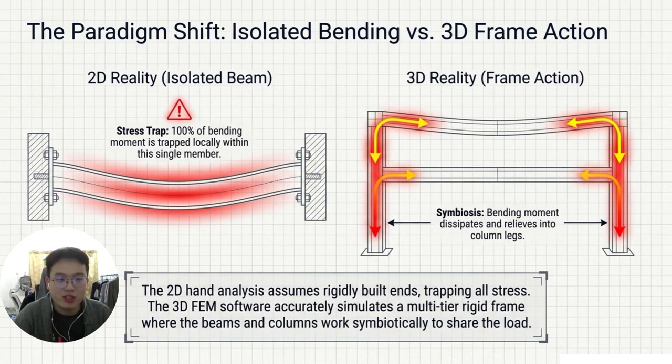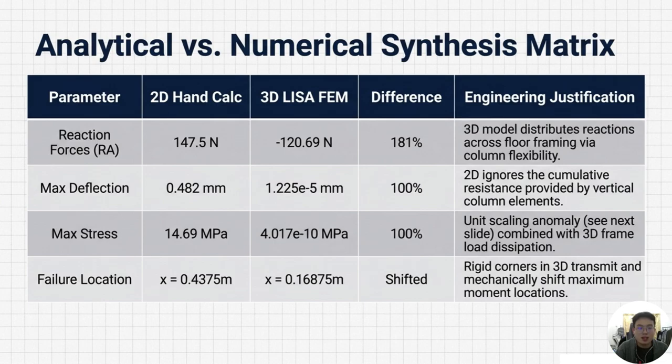This slide shows the deformation behavior of the structure under loading. The largest displacement occurs near the central region of the loaded members, which is consistent with beam bending theory. However, the overall deformation remains relatively small, indicating adequate structural stiffness. This slide compares the analytical calculations with the finite element results. Although some differences exist due to the modeling assumptions, both methods show similar structural behavior and confirm that the work table remains safe under the applied loading conditions. The comparison also validates the accuracy and reliability of the finite element model.